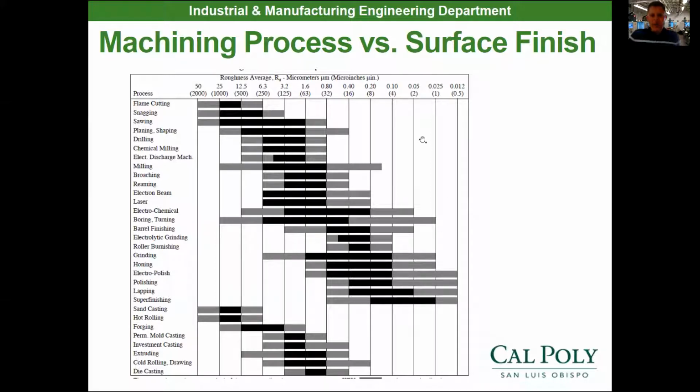So when I start to look at the roughness average here, that's how you measure surface finish, Ra. We talked about that in 145, right, with the screwdriver. But if we're in Kevin's class and we're flame cutting stuff, you probably have done that if you've been to his class, you get horrible surface finish if you remember that, right? So if we look at that, our roughness average is not doing so well there in microinches, right?